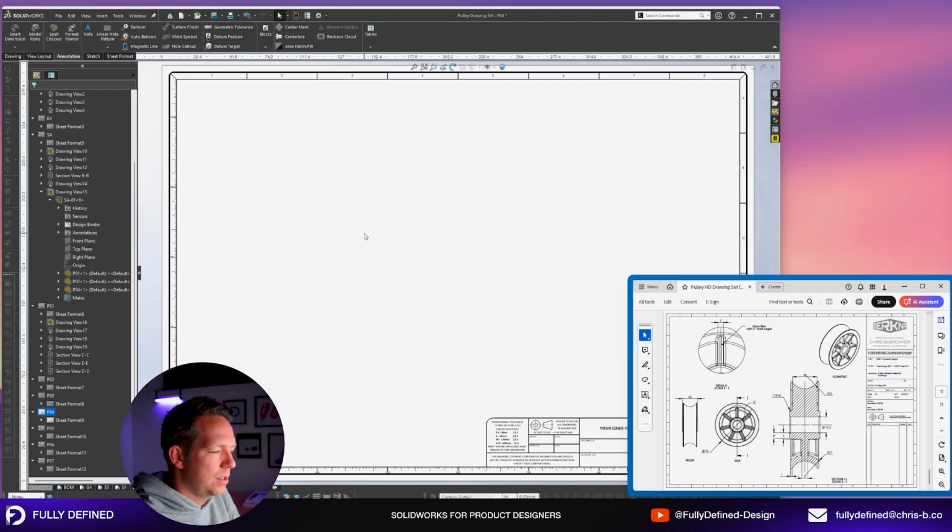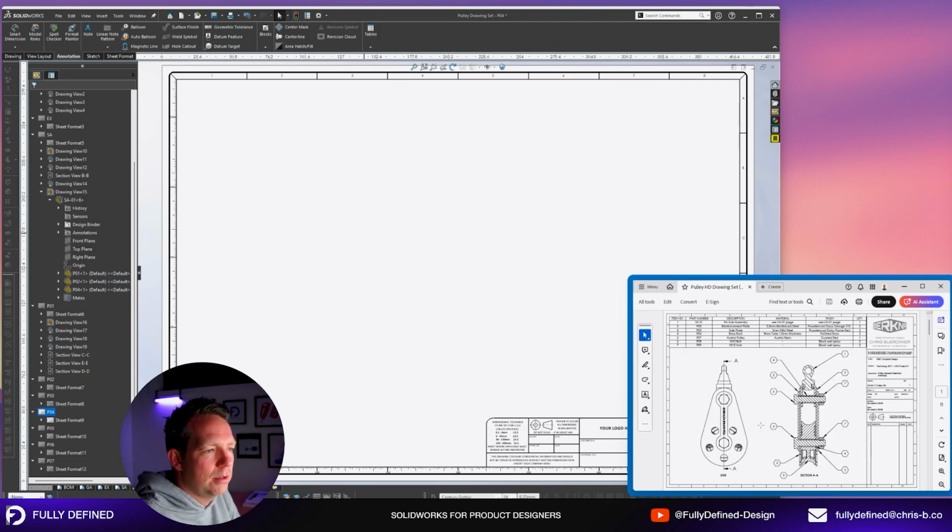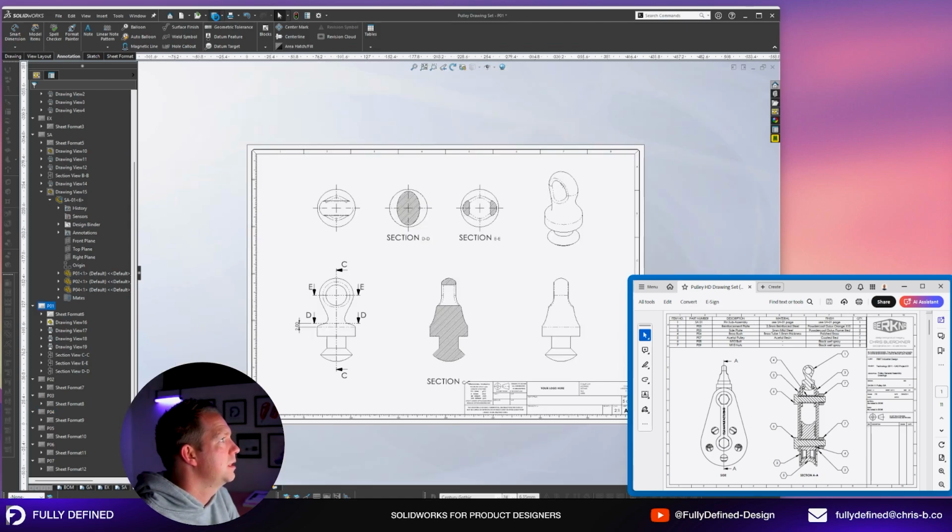In this case, we're using a standard, I think it was M10 bolt, 45 long with a hex head. There is no need to specify a drawing for a part such as this. Instead, a note in our bill of materials to say the size or the spec will be sufficient. So we're not going to do separate drawings for those parts, but they are going to be listed in the bill of materials. All right, so let's continue on.